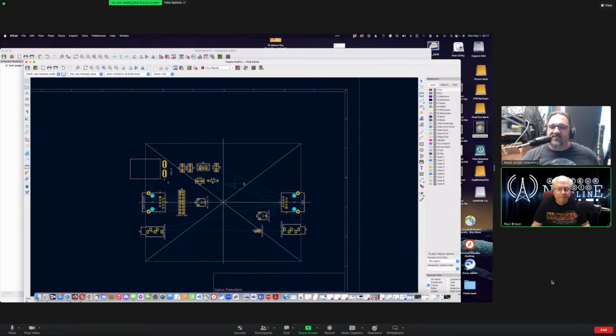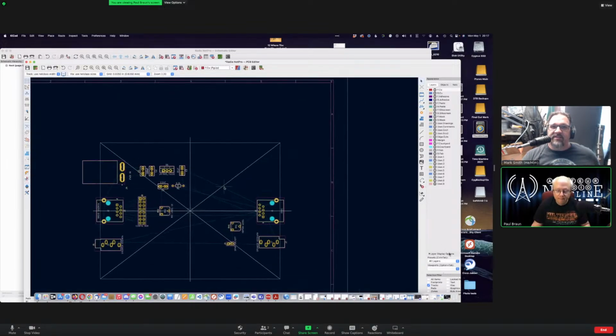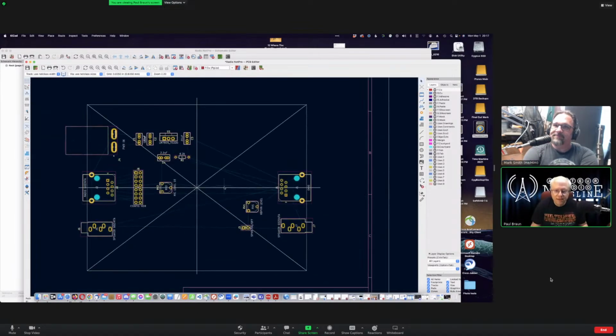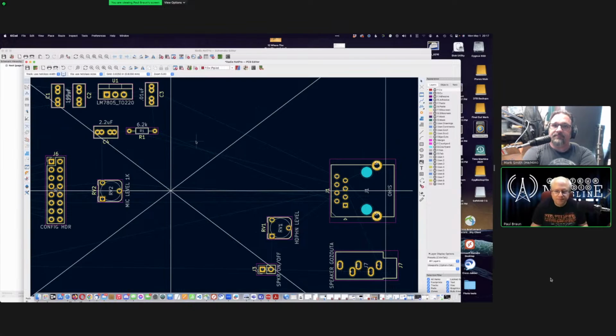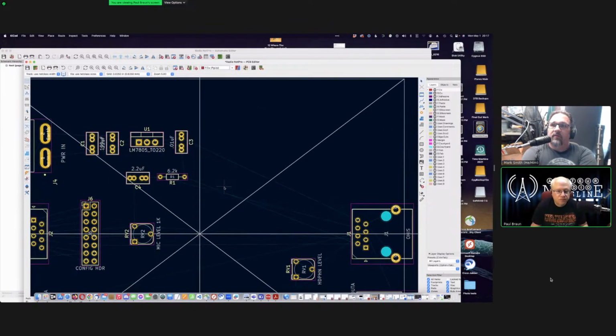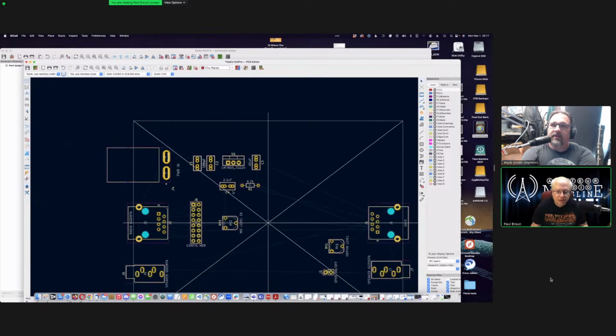It looks like it didn't select anything, but if you do Control-A, delete, after selecting only tracks on the selection filter, that will delete all your tracks. There must not be any left, because nothing got highlighted. So turn all your items back on, otherwise you're not going to be able to operate with anything. Okay.